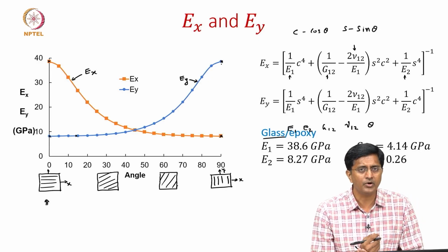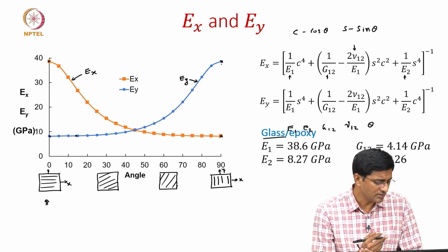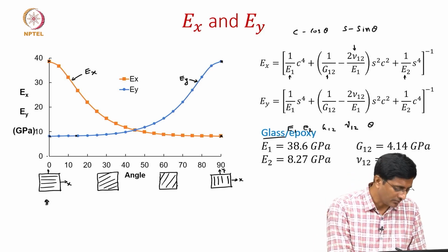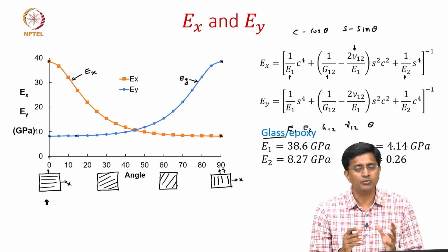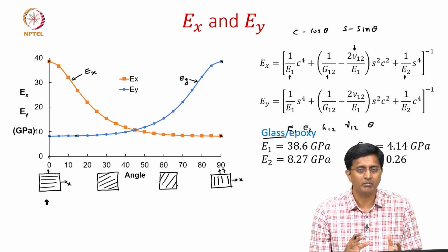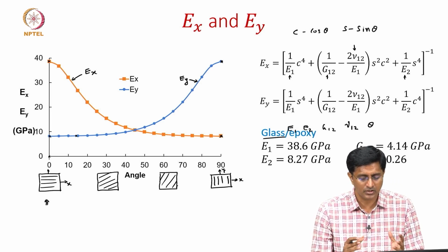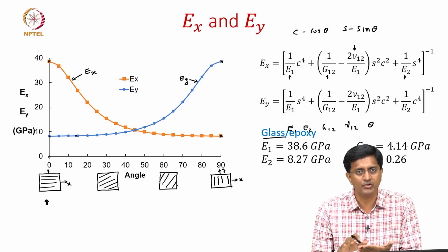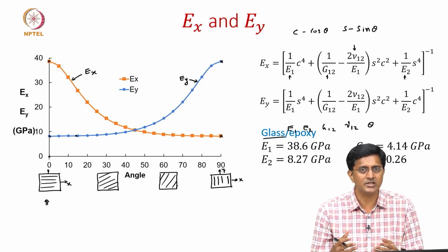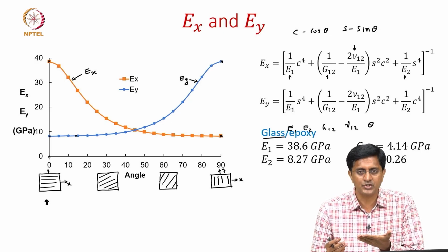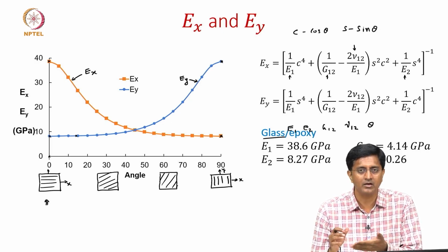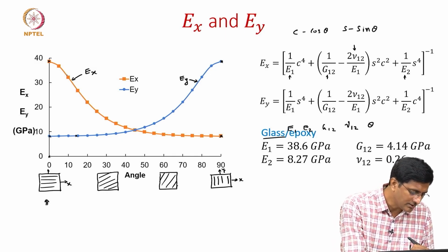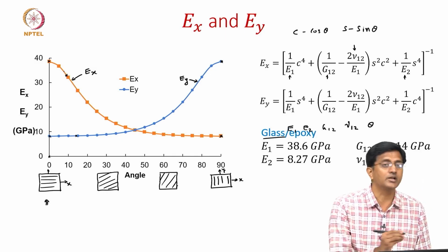So, one very important point for us to look at here is, though we know that the properties are high at an angle of 0, most times these composites are prepared manually, using hands to align the fibers along the direction where we want maximum load. But there is always a chance for human error. Let us say instead of aligning at 0, there is an angle error of 10 degrees. At 10 degrees you already see there is a drastic reduction in the properties.